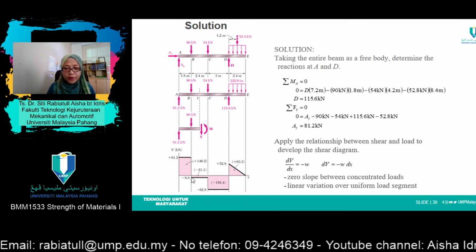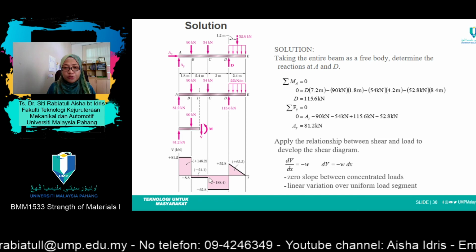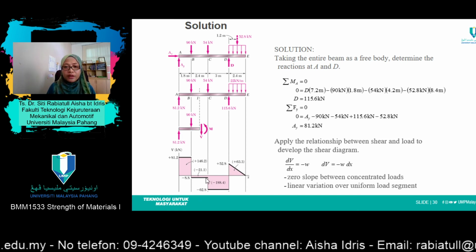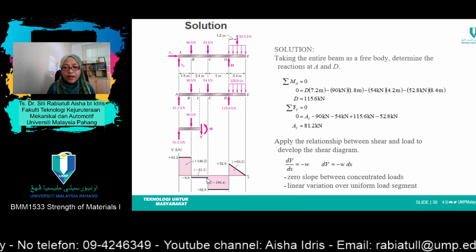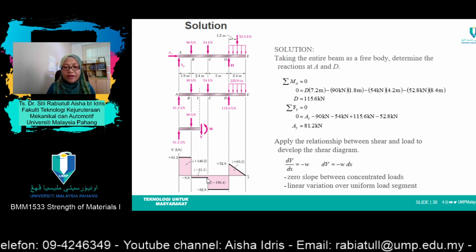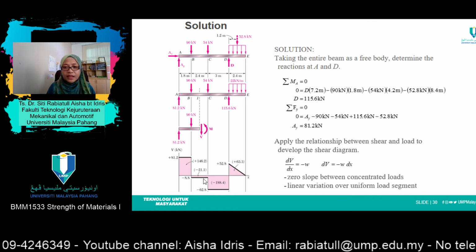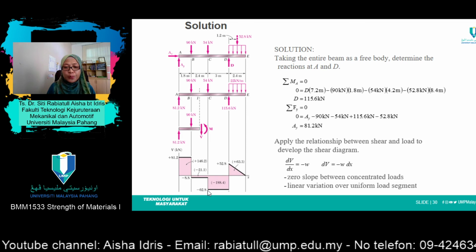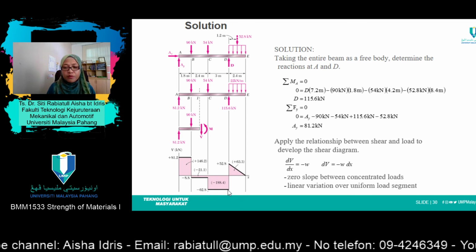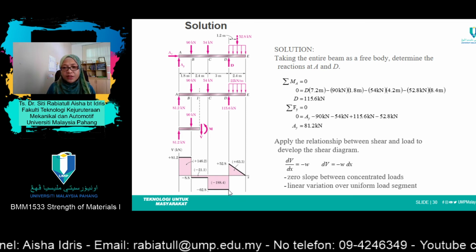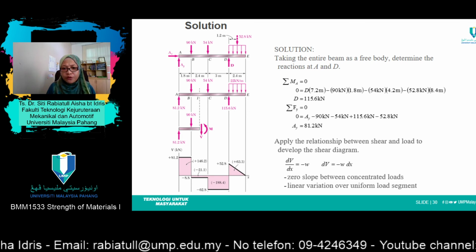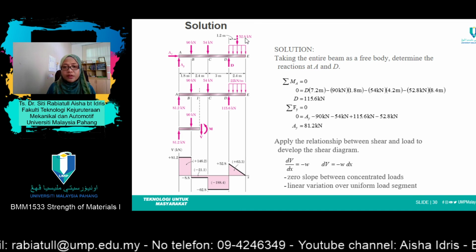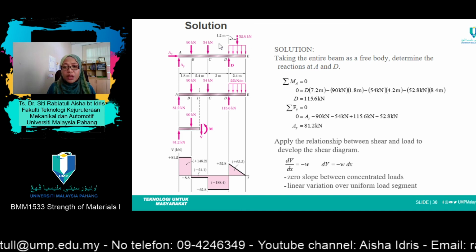So at this point, after that, moving to point C here, you'll find 54 kilonewton load acting on C. So negative 8.8 plus negative 54, you'll get the value of negative 62.8. So this one moving to point D. Until point D, there's the uniform distributed load there.